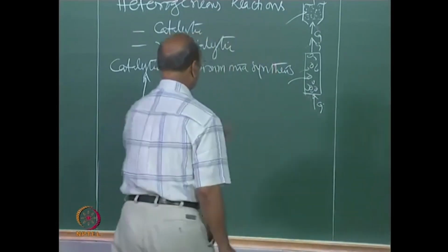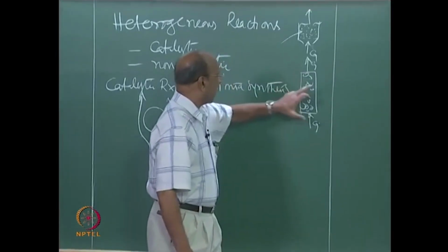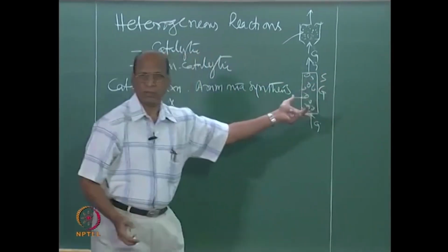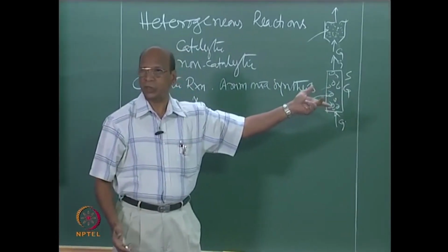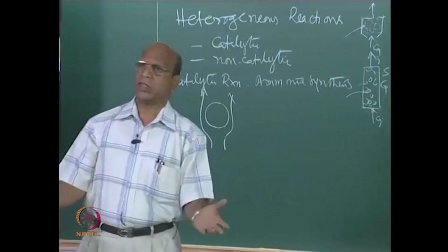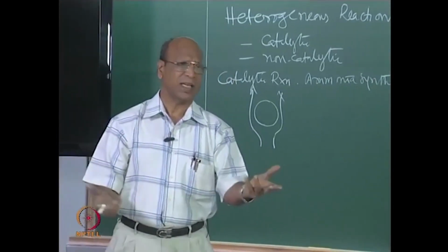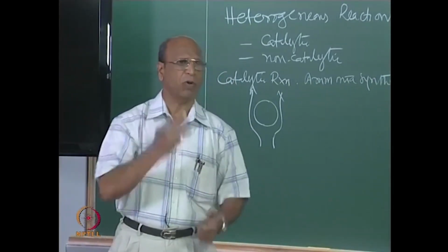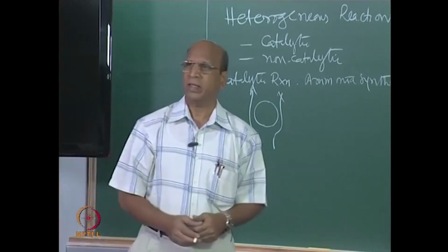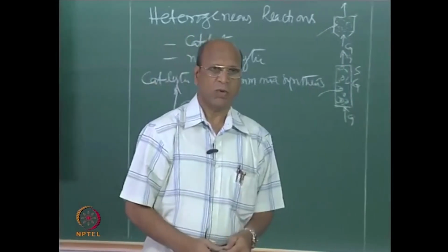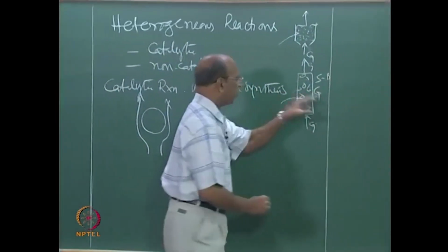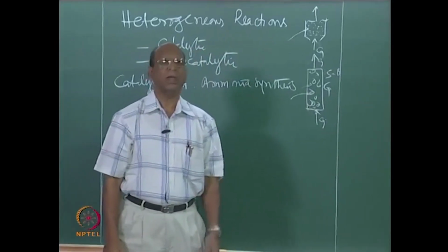So when I talk about this packed bed, I have solid phase and gas phase. These two, non-catalytic gas solid reaction. So now I have to tell what is the contacting pattern for solid in a packed bed. We have only three: batch, plug flow, mixed flow. Batch. Why? Because solids are not moving, they are there. So this is batch. And what about gas? How is it moving? It is plug flow.